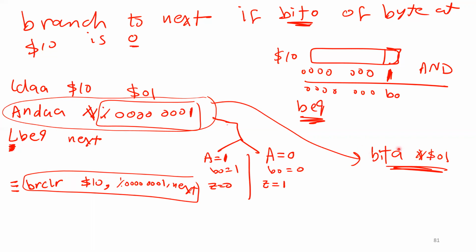Is that okay? So what is this one going to do? This one is going to do AND operation, number 1. Number 2, update the flags, right? That's it. The result is not going to be stored in A. So this one is not going to change A, but the other one is going to change A. Anyway, if this is okay for you and you don't care if you destroy it, that's okay. No big difference between them. Any question, guys? Okay.